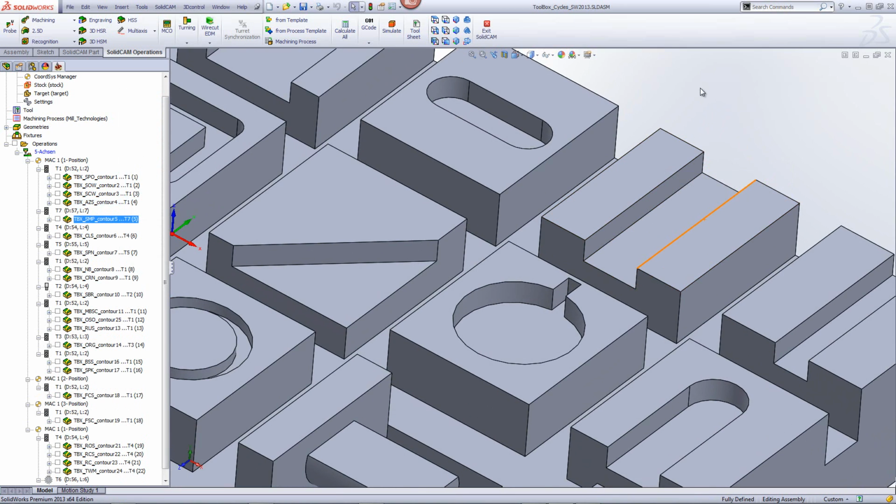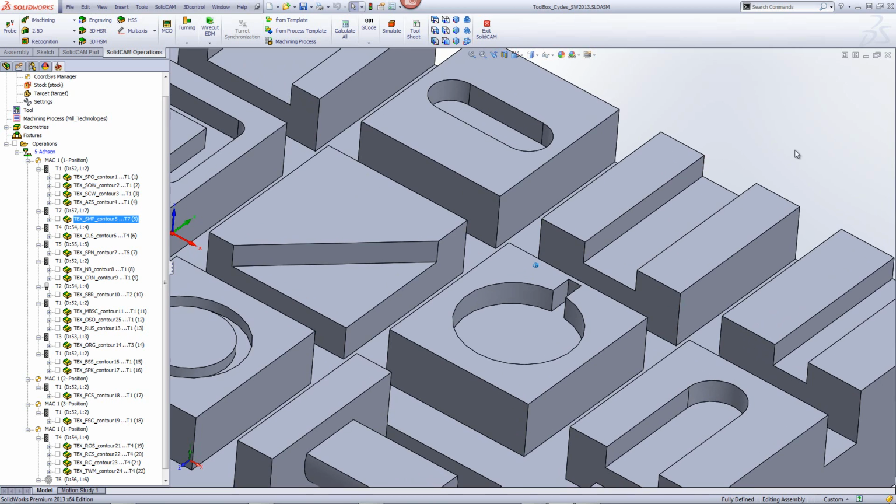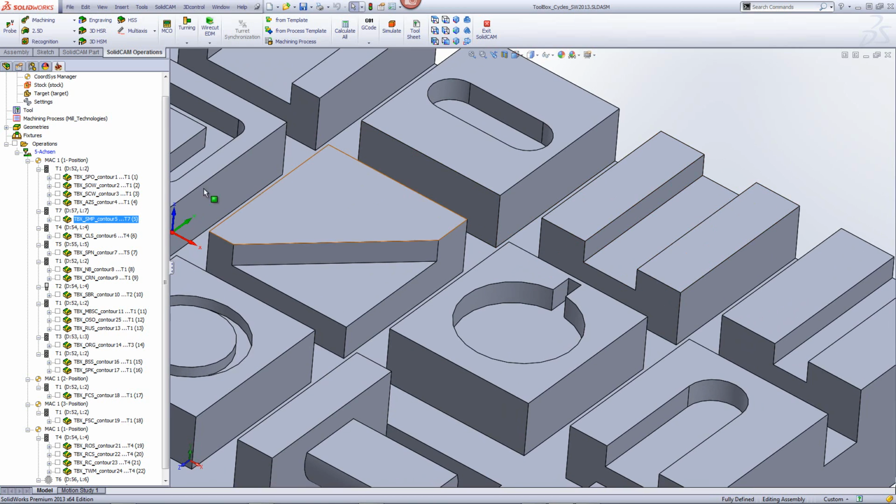Now, in our next operation, I like to work in this particular area over here. This is what we call a simple slot. All we want is to have the tool go down, across on one side, then go directly to the other side without going up to its clearance area, and then coming back down. And I'd like to do this without having to create a chain that goes across over there as well, just by picking these two elements.